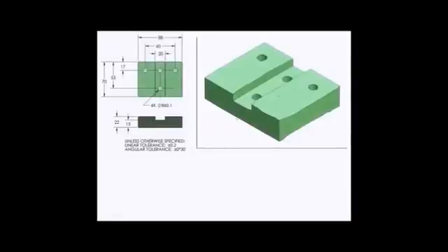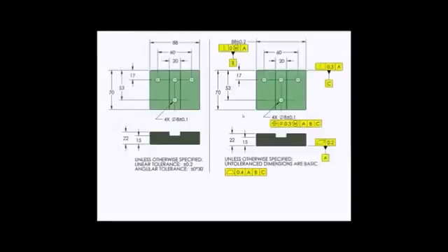The trouble is, parts is parts. We can't make perfect parts. And I don't care how good the machinist or the tool maker is, parts distort due to stress relief and heat treat and on and on. With just a few mouse clicks, I can create a drawing that takes away all these problems. Now I have datum features that establish the origins of measurement. I have position on the holes, I have a general profile that locates the surfaces, and this part is completely defined so that we know how much I can be off from perfect.